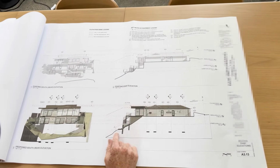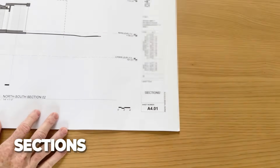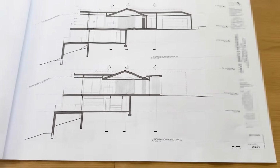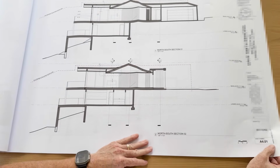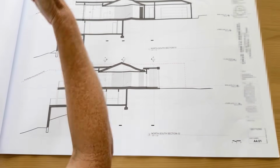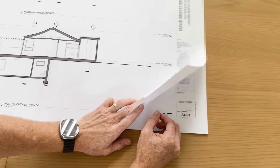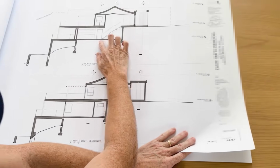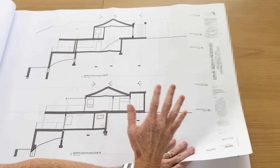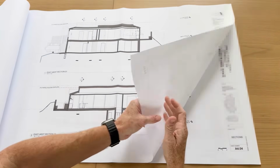And again, all of our notes. As you can see here, we've got our cross sections now, which are referenced back to our elevations. Basically looking at the building, if we were to take a part of the building and cut it down the middle and open it up, this is what cross sections, or sections, are. So we're basically dissecting the building and being able to open it up and take a look at what's inside. These are important if there's a question regarding what type of finish material, how the stairs are going to line up, there could be a number of different reasons why we want to look at cross sections, but more importantly, there's lots of them.